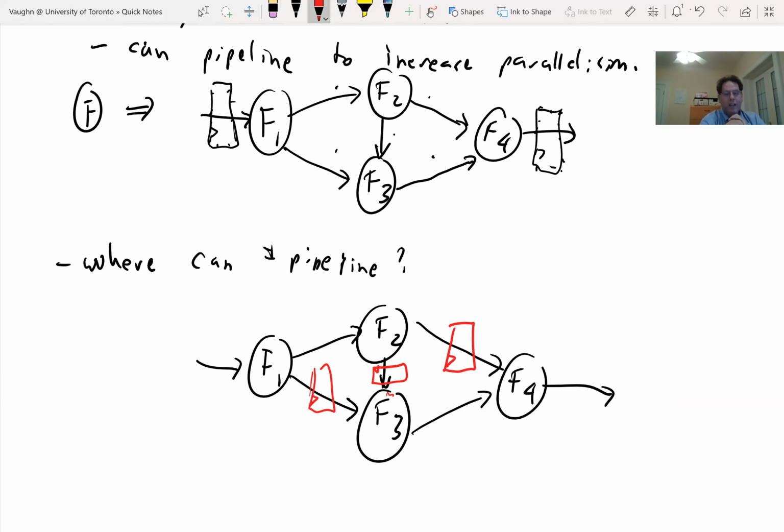So I just added latency to my design. Did I add more latency to certain paths than other ones? Because if I did, it's broken. If I match them all, then it's delayed. Everything comes out, for example, 1 cycle later, but other than the fact that everything comes out 1 cycle later, I do the same computation. Yeah, so people are saying it's legal, and it is.